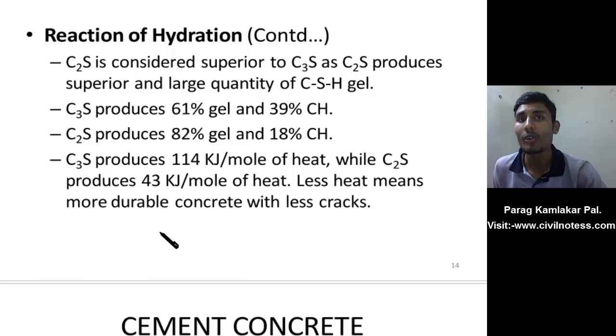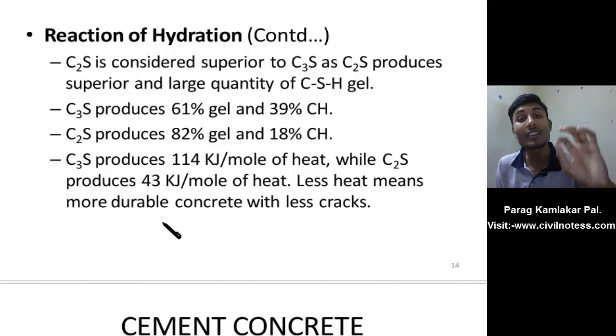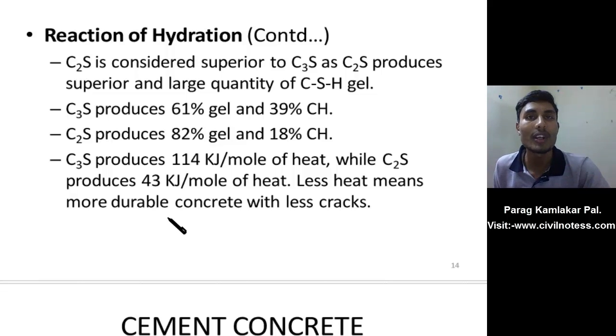But not only heat, the water content is also a parameter which tends to cause cracks. If the water content exceeds 38%, cracks will definitely be there. If the water content is 38% or less, there will be no chances of cracks in the concrete. I'm not saying this from my side; it is what I searched and found. So 38% is a common factor which has to be maintained in the concrete to make it more durable and workable, and to get consistency.